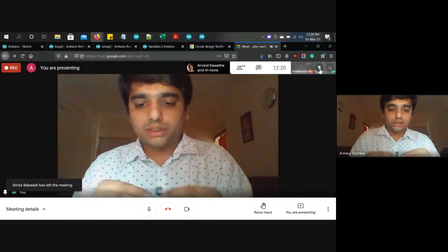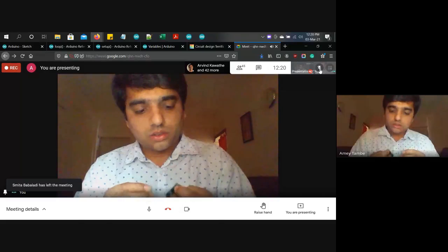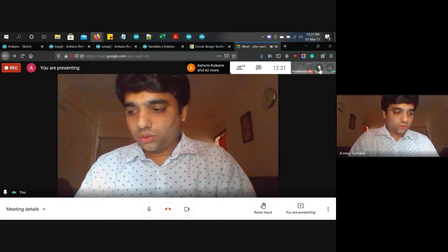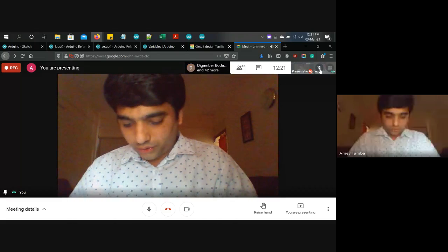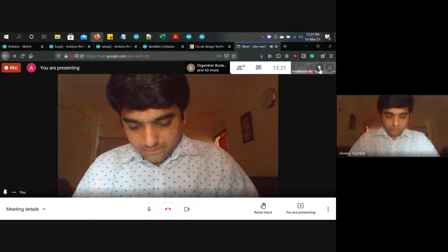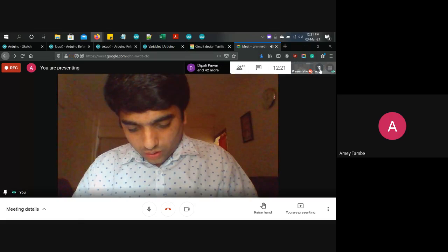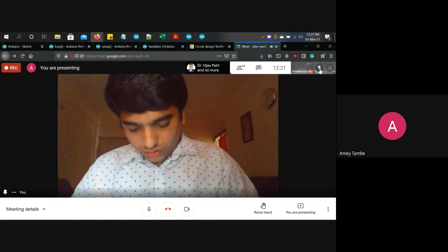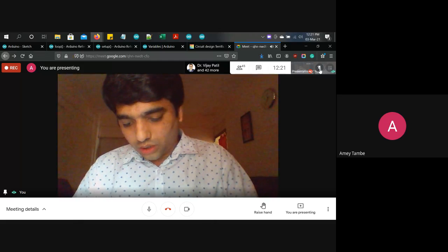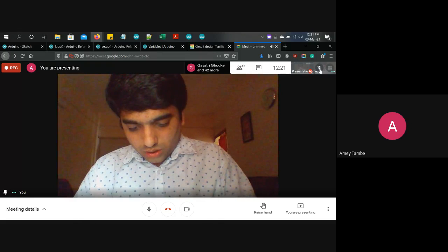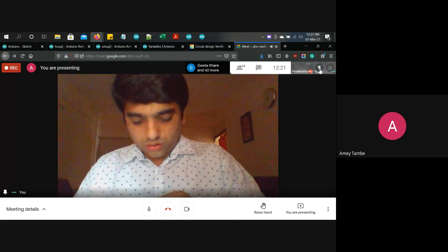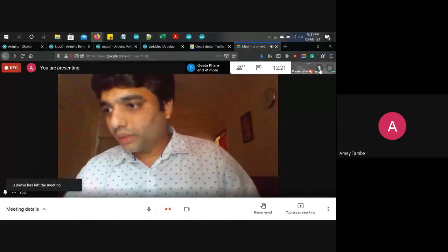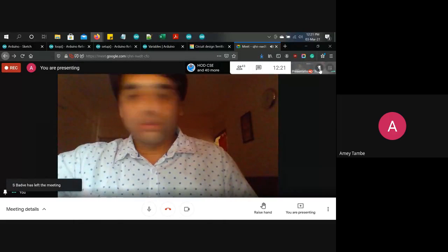Now I've interfaced it. I'll just see which is the VCC. VCC is red, so VCC will go to 5 volt. Ground goes to ground. Then the middle one is the out, which will go to 3, and finally 1 is to ground. This is our circuit done. I'll just program it.